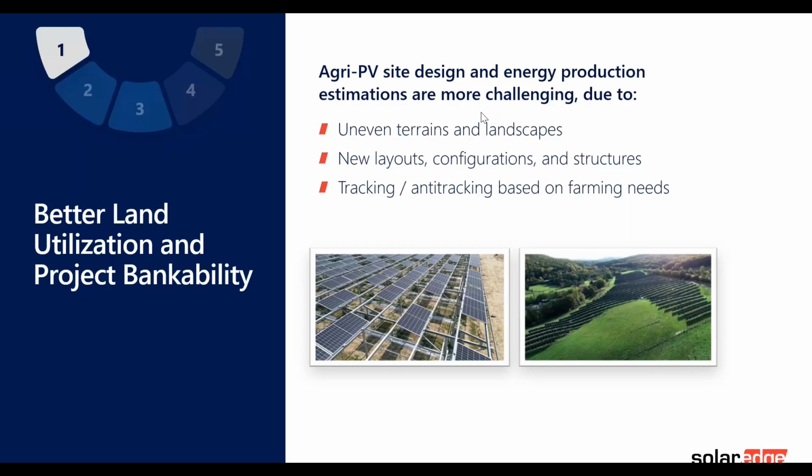The main thing that is important to understand in Agri PV is that unlike other ground mount projects, where basically there is an option to do groundwork and make the land more suitable for solar energy production, in Agri PV it's quite the opposite. The PV system must adjust or be adjusted to the existing situation on the farm or on the land.